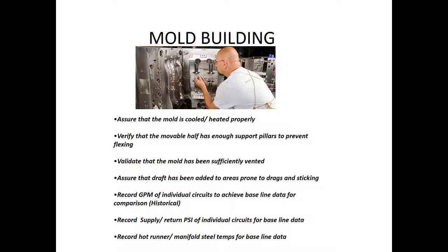Another thing that we're going to record is a supply and return pressure of individual circuits for baseline data. And we're also going to record hot runner manifold steel temperatures for baseline data for comparison when we run into problems.